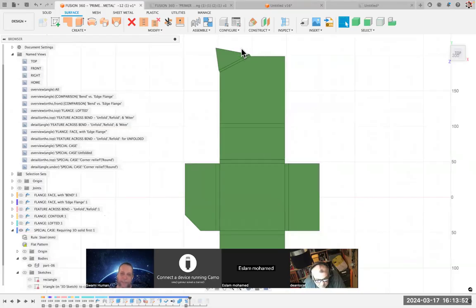And again, this is the problem area up here because we've defined things by the distances and not by an angle. And even if you had to do it at an angle, it might be difficult to do. The 90-degree angles are simple. It's when you have something different, not 90 and based on other things. So it doesn't just extend this. It's not just this corner bent, right? If you just bent this corner, you don't have enough material to cover the gap, cover the hole you made in that corner.